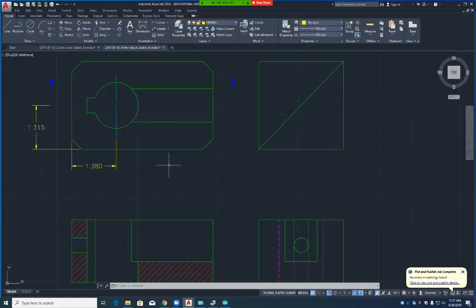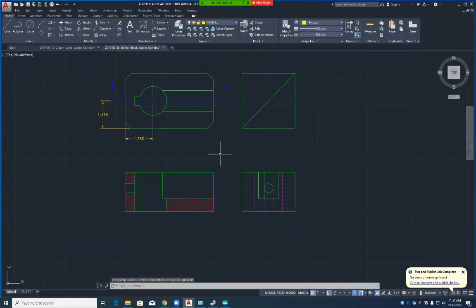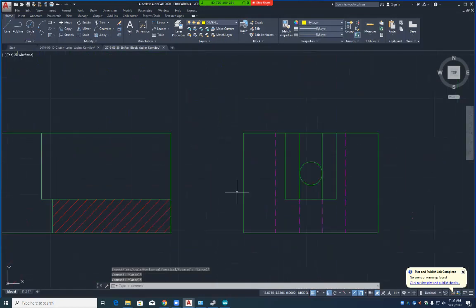Exactly. You see how this is? It's a 1/2 inch out from your cutting plane line. So don't make that mistake on your drawings when you turn them in, okay? Now we're going to put the diameter of our hole in here. And everyone knows how to fix this right here, don't you? Click it, and click it again, and then drag the center out. My ortho's on, so I can put it anywhere I want. Right there. That makes sense?